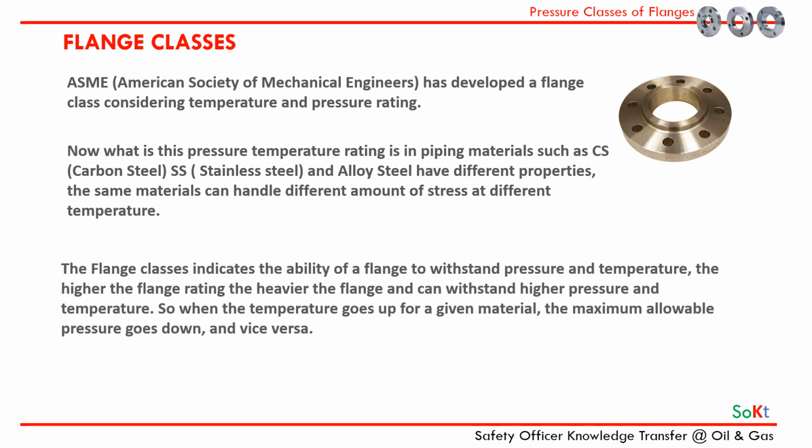The flange class or rating indicates the ability of a flange to withstand pressure and temperature. The higher the flange rating, the heavier the flange and it can withstand higher pressure and temperature. So when the temperature goes up for a given material, the maximum allowable pressure goes down and vice versa.